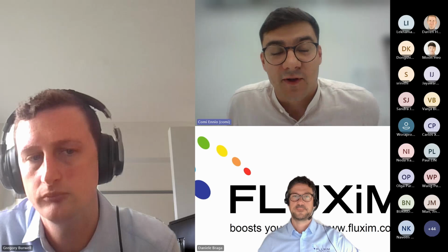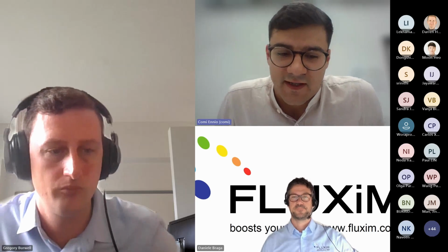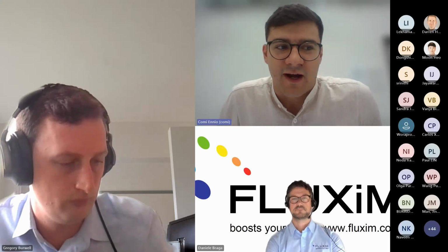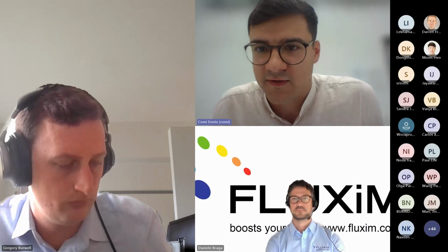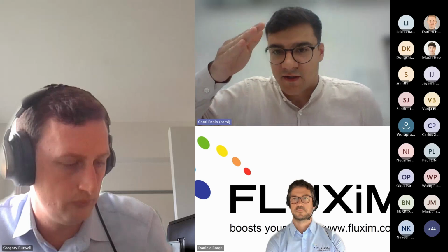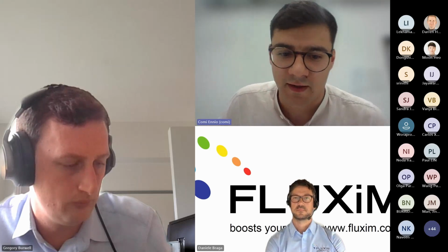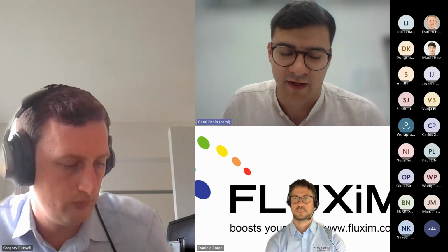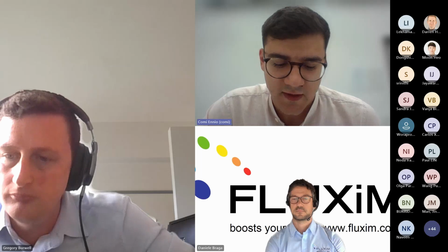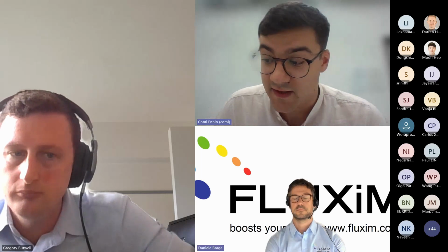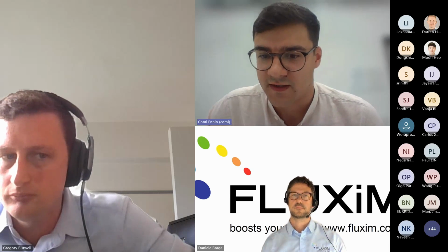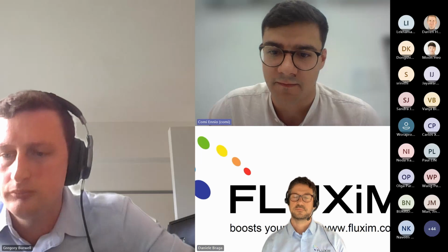Yeah, we applied voltage for a very long time to those devices, and we saw that the EL just continued to increase for hours and hours. In a few devices, the EL reached the top at about 8 hours, and then also the current stopped dropping, so it kind of topped out. And then the other question was about VOC. Yes, while the EL signal increases, the VOC also increases at the same time. So this behaves very similarly.